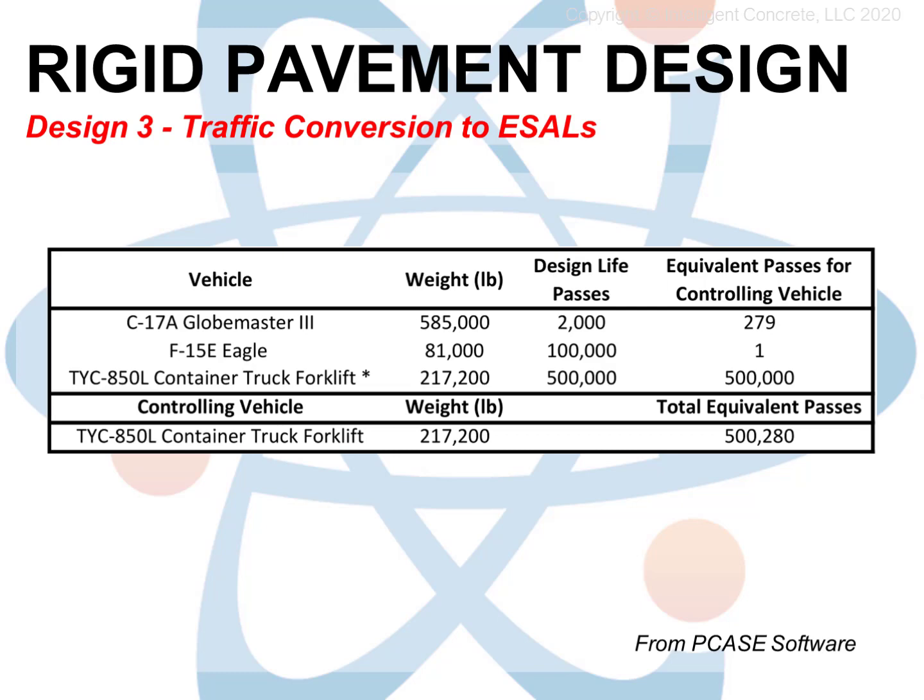Do not worry about how to make this switch. Only know that different pavements, particularly airfield pavements, have different equivalent axle loads used for their designs. We're just trying to bring everything back to a single uniform number from which we can base the design. Roadways typically use the 18,000-pound ESAL, but for airfields, to use a tractor trailer as the design vehicle would not make a lot of sense.